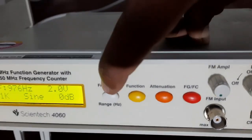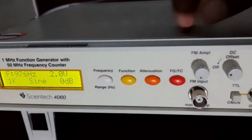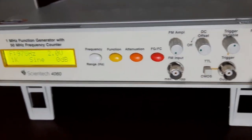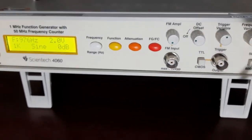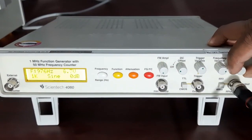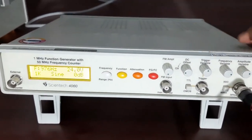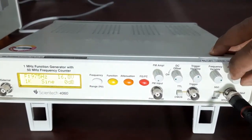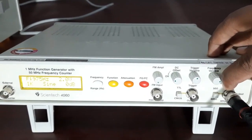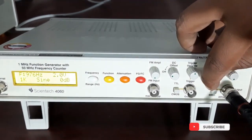And you can see we have so many types of buttons like frequency, function, attenuation. We can use these buttons in order to change the parameters of the wave. Now you can see, if I increase the value of the amplitude variable, the voltage on the screen is increasing, like 23, now it is 24.04, the maximum value. Now if I decrease again, the amplitude on the screen will decrease. Ultimately we are changing the amplitude of the wave coming out of the function generator.